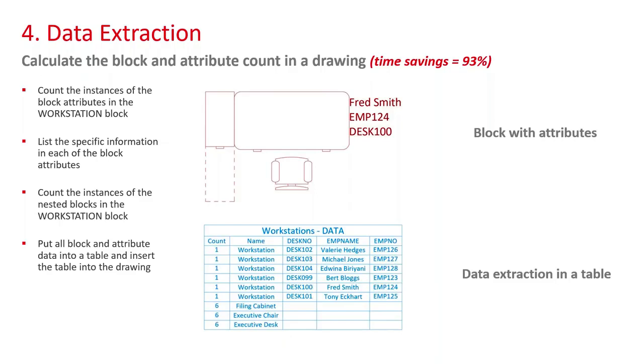And all of that information can be taken out of your drawing and put into, as you can see there, an AutoCAD table, or it can go externally. It can go to something like an Excel spreadsheet or an Access database in an MDB file, for example.